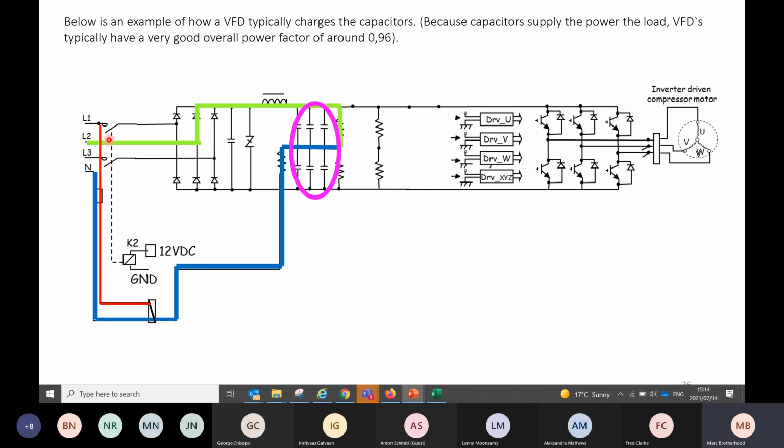What's pretty much happening is we pre-charge these capacitors. The caps now get pre-charged to 320 volts to avoid electromechanical stressing of the components. And these caps also draw massive current. When they're discharged, they're just sitting there. But when they initially charge, the aluminium foil inside draws massive power. And that's why you have that huge current spike as these initially charge. I said to you early on in the training, these can easily stay at 560 volts. But we can't charge them up to 560 volts straight away. We need to warm them up.